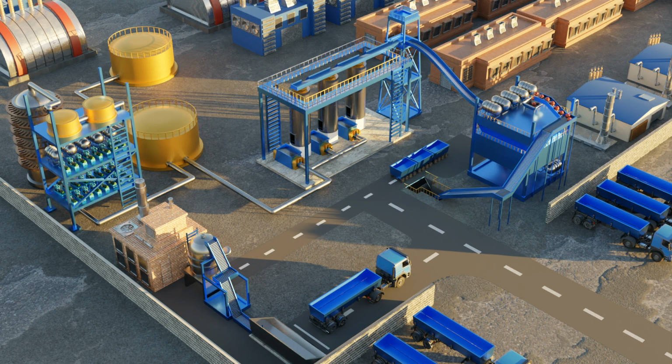The fruit will then be conveyed to the digester, where it is heated and digested. The digested fruit is conveyed to the screw press to press the oil out from the fruit. The oil is inserted into the oil storage tank, where the stored oil will be further delivered to the bleaching and deodorizing process to get the refined palm oil prior to being sold to the market.